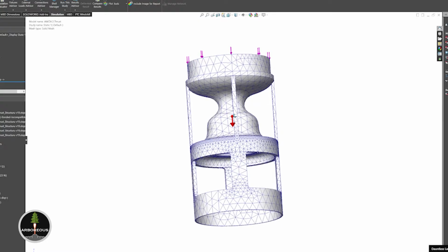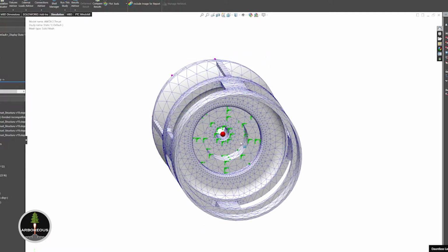The objective of the thrust structure was to transfer the load from the motor into the upper sections of the vehicle. Our initial design was a simple cylinder with internal geometry that was used to mount the motor. Through mass optimization, we were able to understand the load paths that would be seen and redesign it.